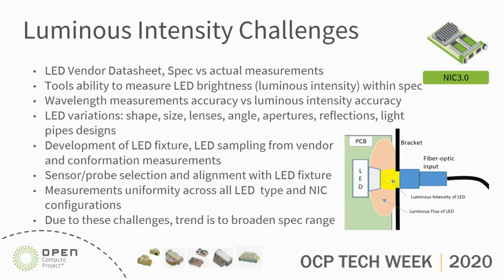Testing tools' ability to measure LED brightness and its luminous intensity within the spec showed that instruments and tools are available for brightness measurements, but most of them are designed to measure LED brightness for light fixtures in a room or in an appliance. Wavelength measurement accuracy versus luminous intensity accuracy became significantly different.